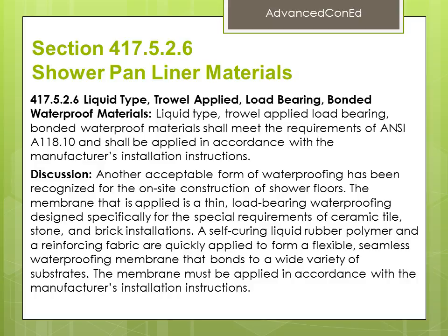Section 417.5.2.6 Shower Pan Liner Materials. 417.5.2.6 Liquid type, trowel applied, load bearing, bonded waterproof materials. Liquid type, trowel applied, load bearing, bonded waterproof materials shall meet the requirements of ANSI A118.10 and shall be applied in accordance with the manufacturer's installation instructions.